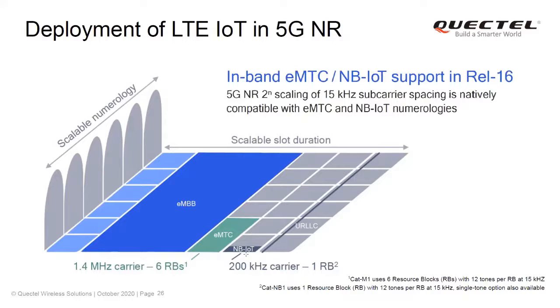So this basically means that for a current NB-IoT device, which is connected to the network, the device doesn't know it works in a 5G environment, but on the network side, the network which is evolved, which supports 5G, recognizes that this is a Cat-M or NB-IoT device and allocates to it the bandwidth in the spectrum this device is using. So it actually includes this, let's say, older technology device in the new technology spectrum.